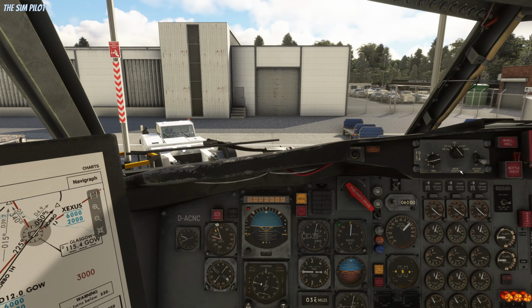Our stop altitude is selected. We can select the heading mode and turn on the flight director to pre-select a 7.5 degree climb. That's after takeoff for our initial climb to cruise. So our takeoff pitch will be 17 degrees.